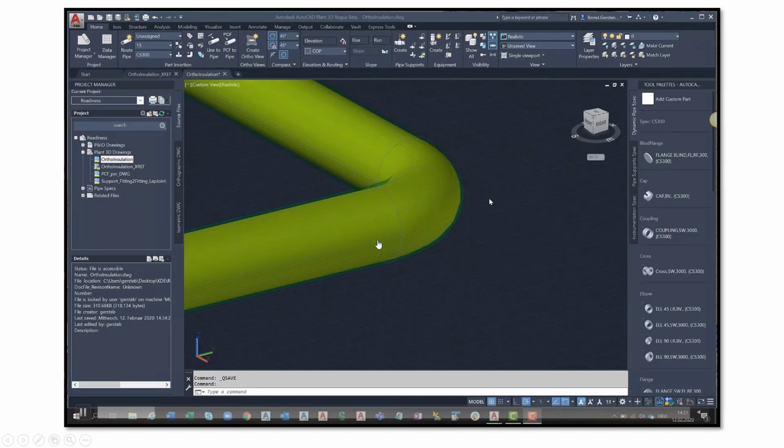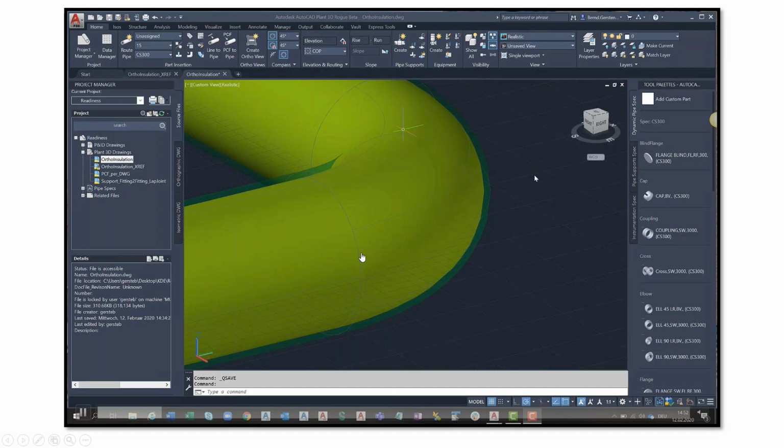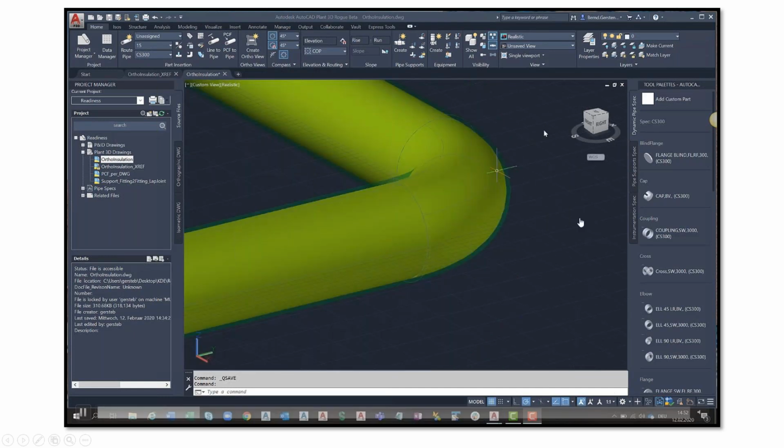You can see this is a Plant 3D model where we've assigned an insulation thickness. This is a very small insulation thickness around this elbow and this pipe here. You can see that sort of halo effect. It's a transparency. It's on a separate layer in the 3D model, and it has a transparency. I think the default is set to 70%, and so you should be seeing that here within a few seconds. This is toggled on using the ribbon. You can see up here there's the insulation toggle, and it is available to be displayed now in this mode.